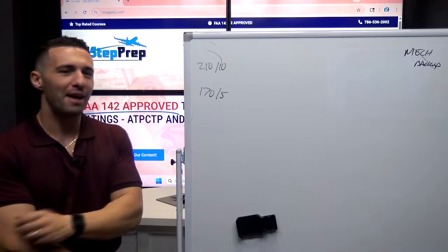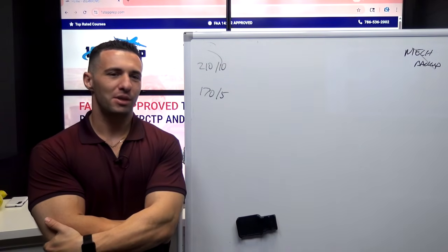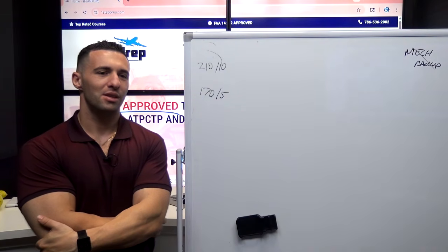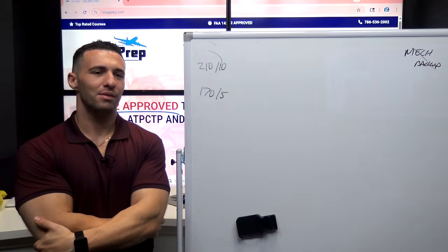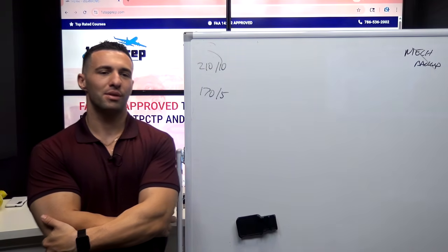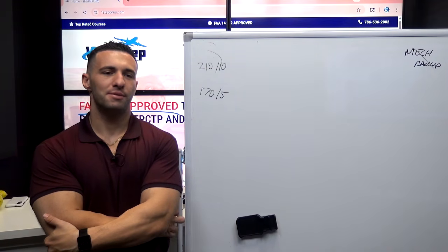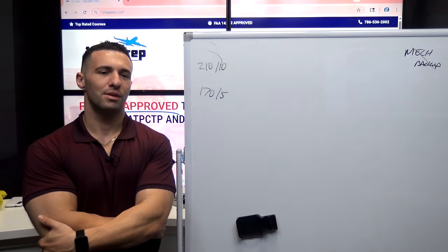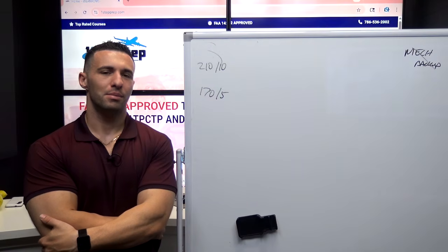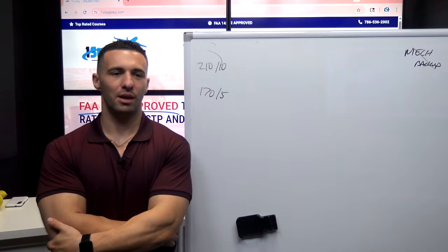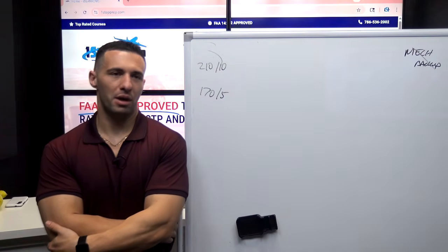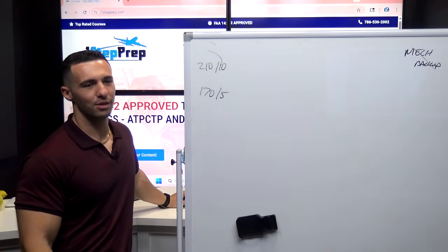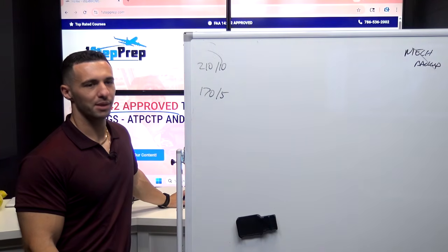Let's assume we depart heavy, with a big discrepancy between V2 plus 10 and S speed. Heavy takeoff. If there is a speed limitation on the first turn of the engine-out SID, would you think selecting flaps 2 would be a better option if we depart with flaps 1? I would just get speed relief, to be honest. You could do that, but I would just tell ATC, we're heavy, unable to speed. Okay, speed at your discretion. That's probably what's going to happen. I think that'd be easier than worrying about the flaps.